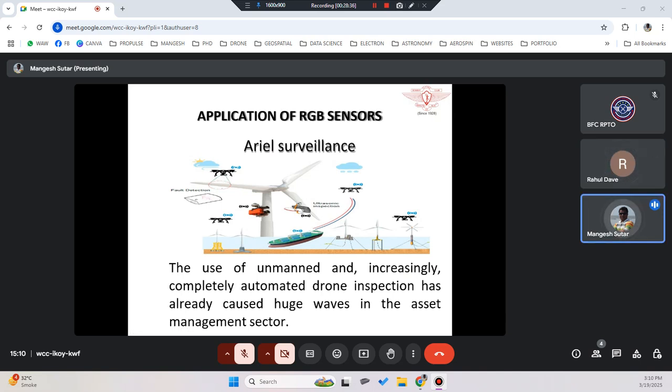A lot of times there are rivets. If you look closely at an aircraft, it is not made of a single structure. A lot of times the aluminum plates are stuck to each other using rivets. Over the period of usage, wear and tear, even these rivets sometimes break, get damaged or become loose. Sometimes you are not able to see them properly, as they are in very difficult locations or positions. In that scenario, the drone comes in very handy, and whatever the possibility of human negligence, the drone can effectively help you do the inspections of those particular things.